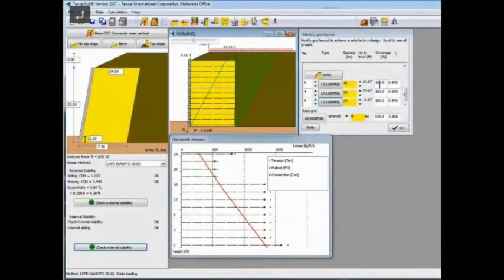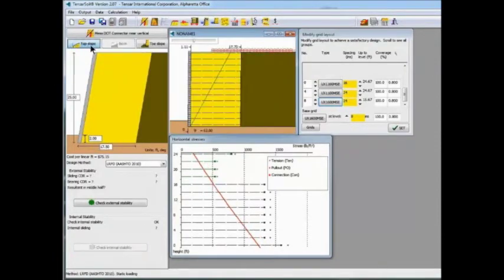Typically the geogrid is at 100% coverage in plan view, so one roll of geogrid abuts directly up against another roll of geogrid, side by side. What you can do is separate out some of the layers of geogrids into separate groups and reduce the percent coverage for the wall. That can be helpful if we had some guide rail posts or signposts at a set interval. So let's take off the top slope in this case.